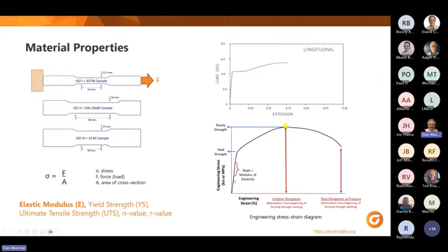So as you're pressing on a curve, it can return to its shape if it stays in the elastic zone. Once you've crossed the yield strength of the material, it starts to stay deformed up until the ultimate tensile strength, at which case it's achieved its maximum. And then depending on the necking availability of the steel that you're working with, it will hang around until it finally breaks at total elongation. So the important aspects on this plot are: we determine the elastic modulus by measuring the slope of the elastic portion of this curve.